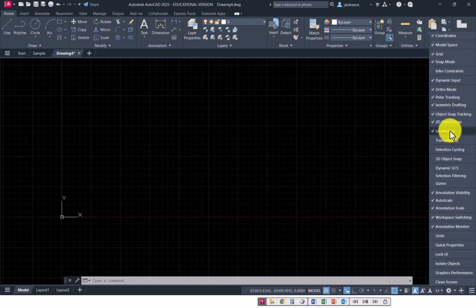Line weight, what line weight is when we start setting up layers, and you're going to do that in chapter 4, you can assign a line thickness or weight to each layer so that the lines are different thicknesses. Because in our drafting standards, hidden lines and center lines are thinner than object lines.